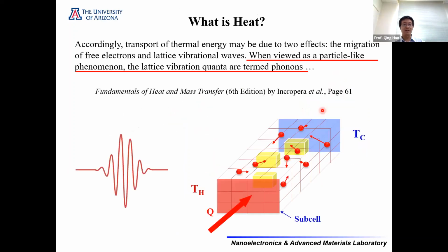A better understanding of the heat transfer inside nanoporous silicon thin film involves a deeper understanding of heat transfer physics. In the undergraduate heat transfer textbook, we learned that in a semiconductor, heat is carried by free electrons and lattice vibration waves. In quantum mechanics, lattice vibration energy is quantized, and the energy quantum is called a phonon, right? So phonon is basically the particle view of heat transfer. In this situation, the thermal transport inside the material can be viewed as phonon transport.